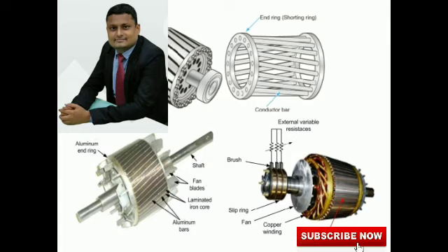Now we come to rotor current. Current through the rotor bars, that is the conductors. So IB equals 6 into IS into TPH into KWS into cos phi divided by SR. You may feel that everything is flowing overhead. So now please keep noting, otherwise you will miss. We have to go very fast.